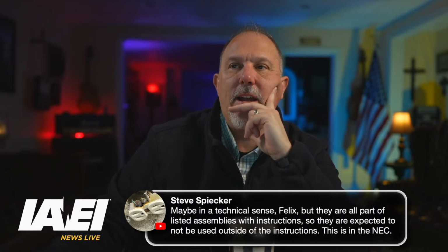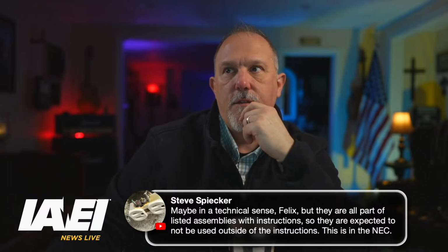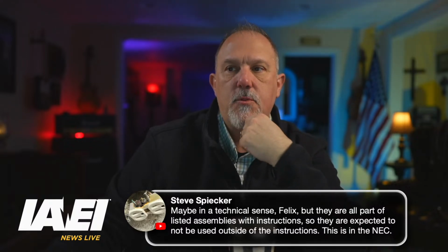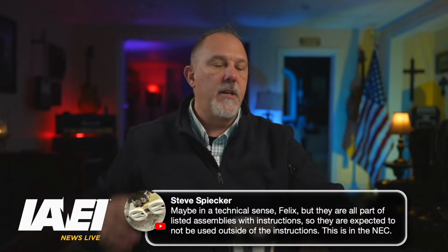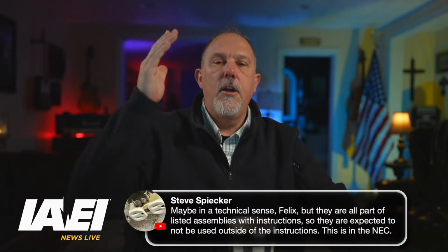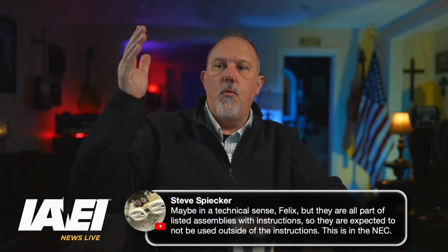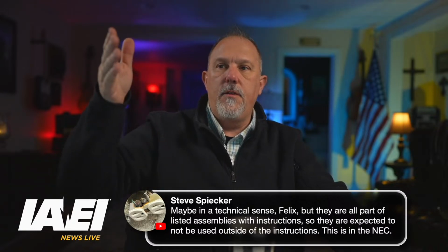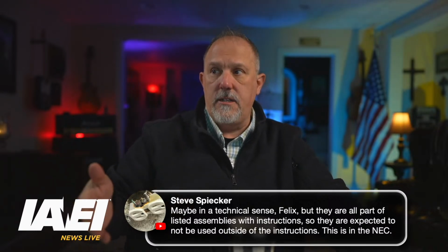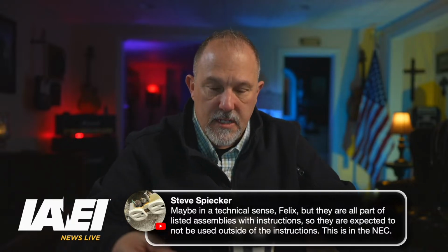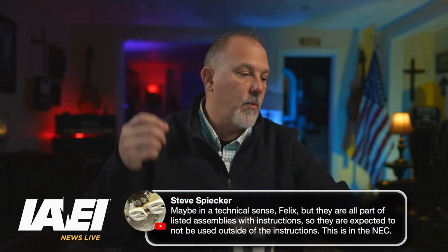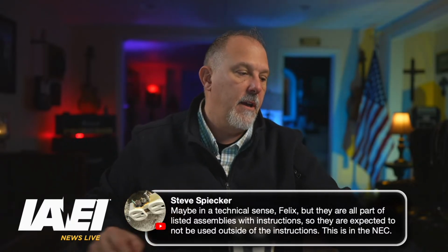So I would still fall back on 240.5 for flexible cords and flexible cables. We use them. Steve, to your point, you're absolutely right. We use them. They are considered protected when they are a part of a listed assembly and they are used in accordance with their listing. That's the fact, Jack.